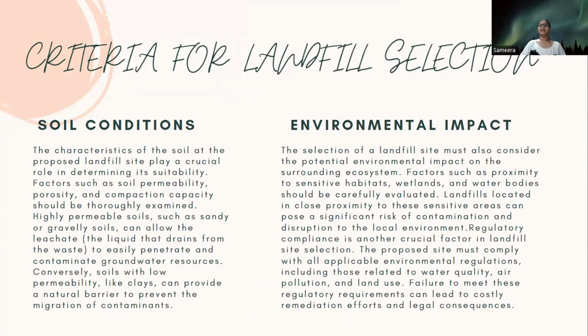Soil conditions. The characteristics of the soil at the proposed landfill site play a crucial role in determining its suitability. Factors such as soil permeability, porosity, and compaction capacity should be thoroughly examined. Highly permeable soils, such as sandy or gravelly soils, can allow the leachate to easily penetrate and contaminate groundwater resources. Conversely, soils with low permeability, like clays, can provide a natural barrier to prevent the migration of contaminants.